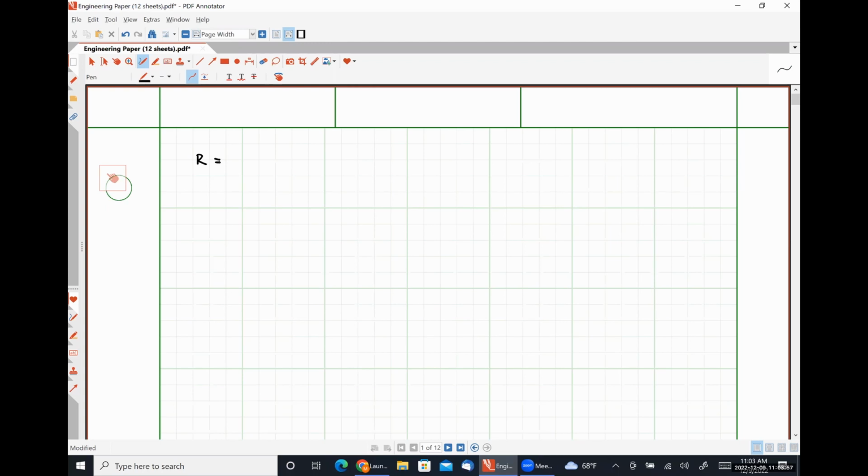There are going to be certain structures that we are going to literally talk about integrating resistances into, so that when the structure experiences some deflection, the resistor itself will experience a change in its geometry, and that change in geometry leads to a change in resistance because of the piezo-resistive effect, and that is going to be one of our sensing tools.